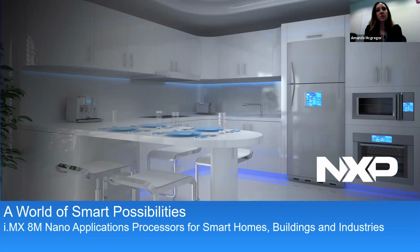Now, LVDS, we do have products with LVDS displays. The i.MX 6, several of them have LVDS display interfaces. We have other 8 products with LVDS. We have other products coming in the future with LVDS that is more of an industrial, larger resolution, or at least physically larger display. If you really need an LVDS panel and you really want an 8M Mini or an 8M Nano or an 8M, there are converters available, MIPI to LVDS, that could be used to give you all the benefits of what we're building, but be able to drive the display that you want to drive.